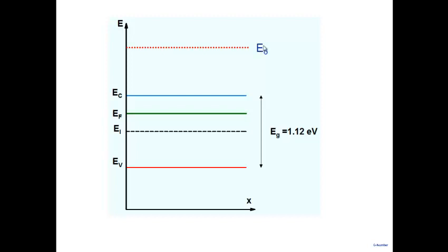It is the value of energy outside a semiconductor, which is imagined to be a vacuum. So what does this energy represent? It is the energy needed to take an electron out from the conduction band to the vacuum outside. It's like I have a semiconductor, I'm ionizing it, removing an electron from the conduction band and putting it into vacuum outside.